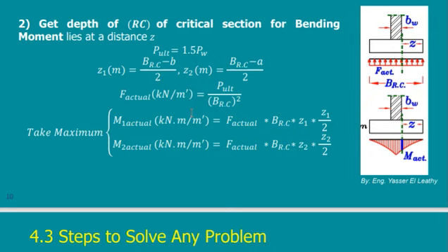This is completely a reinforced concrete part, so I go to the code for reinforced concrete. They use the ultimate load. So I take my previous allowable load, multiply it by 1.5 to get the ultimate load. Then I continue the design using this load instead of the other.